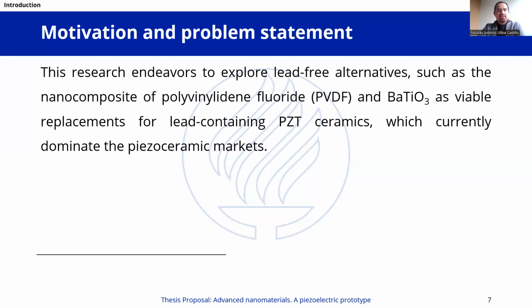And I completely agree. Actually, I would like to mention another one, which, in my opinion, is very important. Enhancing the dispersion of the nanofiller in the polymeric matrix can affect the material's piezoelectric behavior. Therefore, we are very interested in experimental strategies aimed at achieving this goal. So basically, we can start with this issue in order to enhance the piezoelectric response, and then investigate many different processing methodologies to improve it.